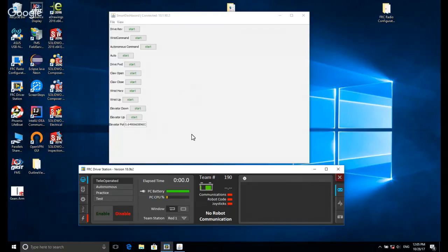So what you end up with when you just do proportional is like this. You have your set point, you have your error over here, and over here you have your motor speed. As your error increases, you're going to increase your motor speed, and this is multiplied by some constant.